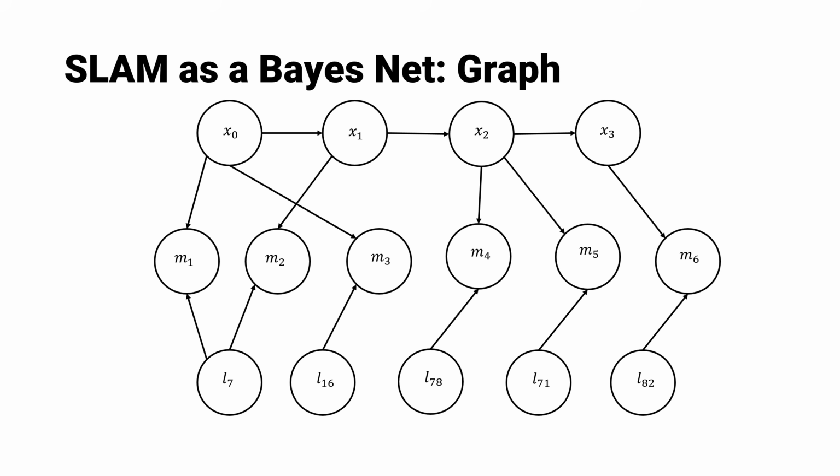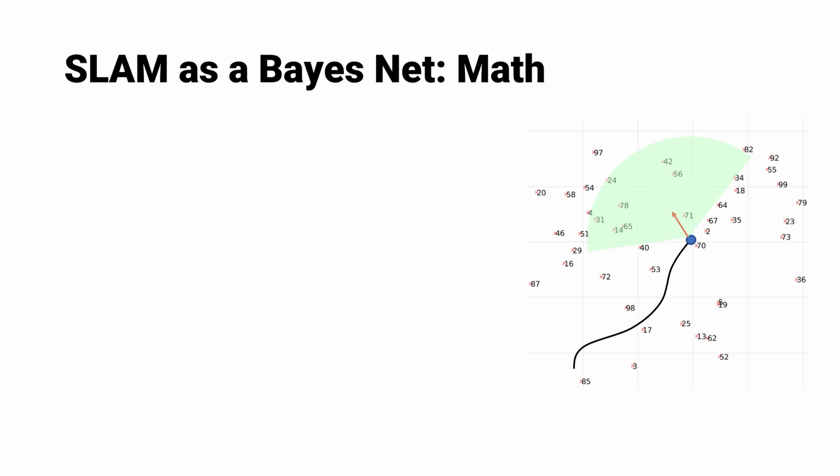We essentially want to say that all of this is correct. What is the maximum probability that these things are right, so that we have the right numbers for the landmark values and the states, given that we have these observations. That's what we are trying to do here. So we essentially want to obtain the trajectory and all these landmark locations, which we have seen in this local map. The motion model is fairly simple. We are essentially saying that we have moved from xt minus 1 to xt, and it's given through this Gaussian distribution, as we see here, with some covariance matrix.